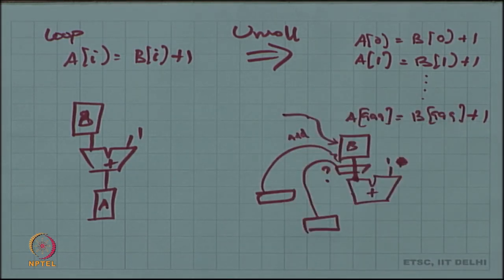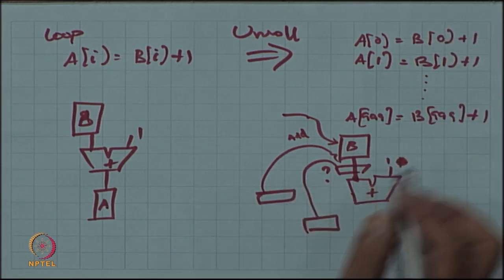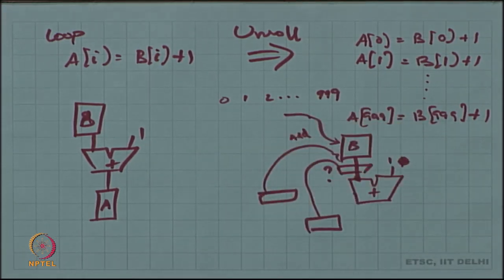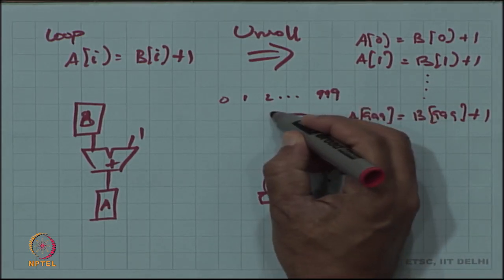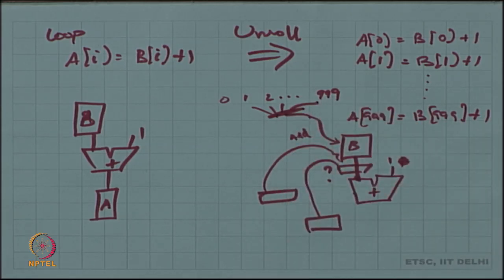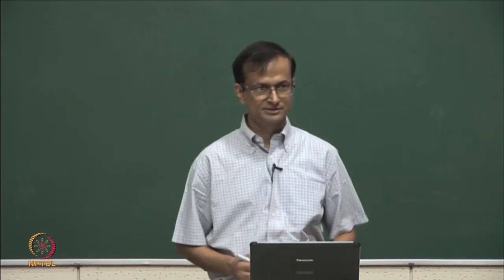What is needed at the address? Anyway, it is a similar kind of an analysis you would have to do. If it is needed, it is fine. So, if I actually treat this as independent constants, yeah, you need to provide paths over here, then it's all right. You are stuck with that large mux that does not show up here, but it actually does show up here. And those mux inputs will be scheduled at different clock cycles. Right. So, but the mux is necessary.